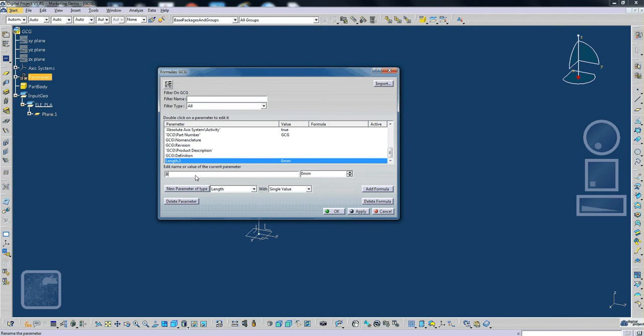So first, called building footprint, BLDG FP dot width. Give it 24, in my case millimeter, so it's 24 meter, right? Click apply. And the next one, name it building footprint length. So this one, give it 42,000. Okay, and then apply.